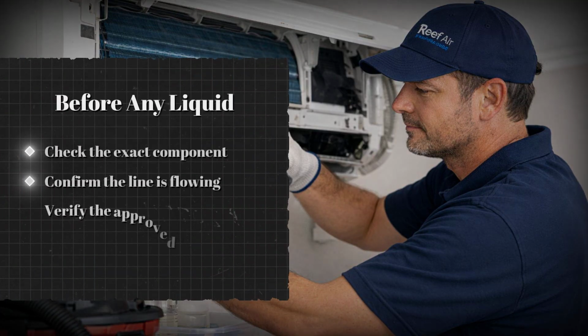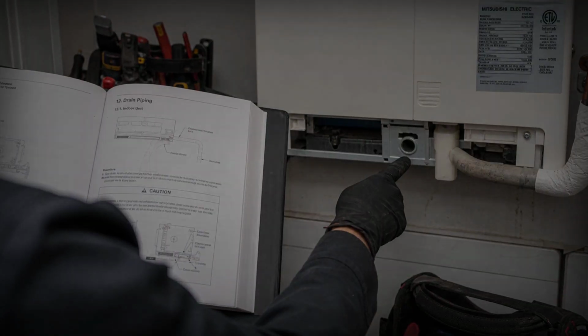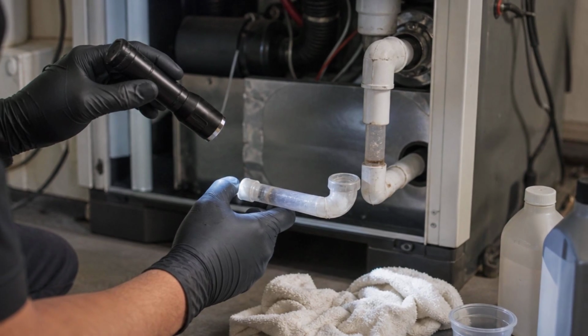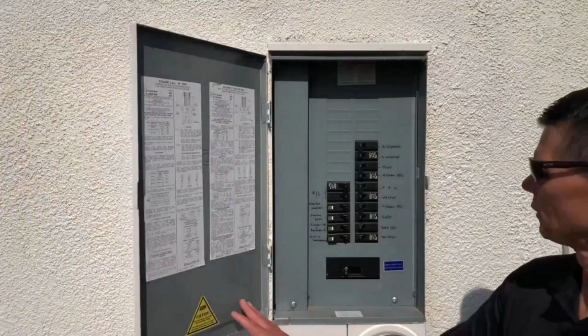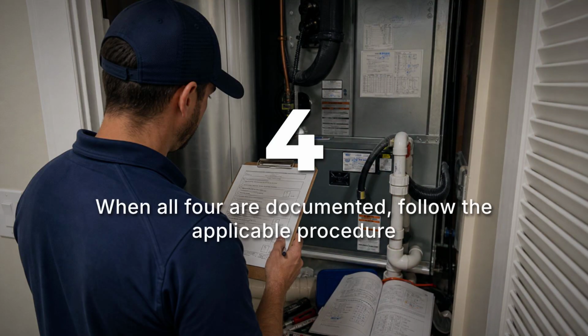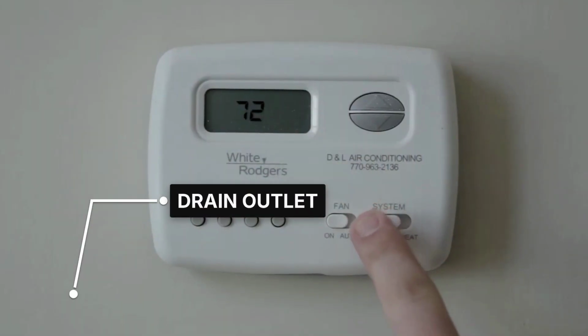Before any liquid goes into your HVAC system, answer 4 questions. What exact component am I touching? Is the line currently flowing? Does the manufacturer name this method for this location? And do I know what chemical, if any, is already present? If any answer is missing, stop at inspection. When all 4 are documented, follow the applicable procedure and verify the result at the drain outlet.